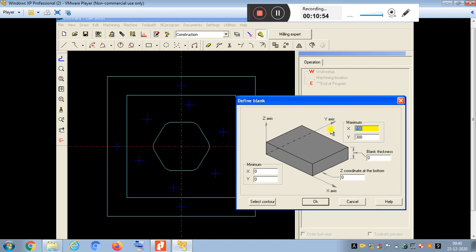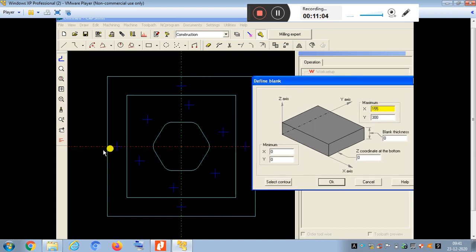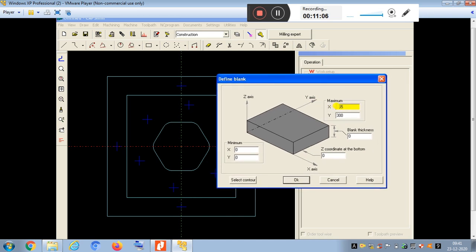So we should be considered greater than that. So then we can machine the part, extra material. Let me consider 5 mm extra. That is the 5 mm on the plus end and the 5 mm on the negative end. Totally 10 mm. Okay. So maximum 155.